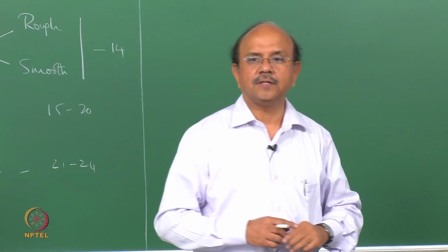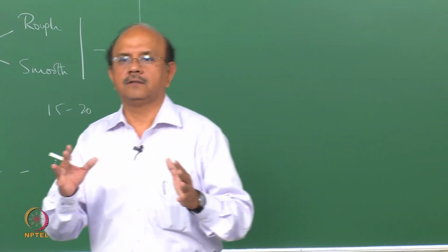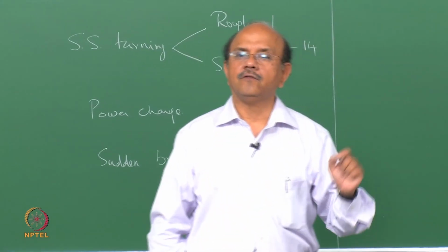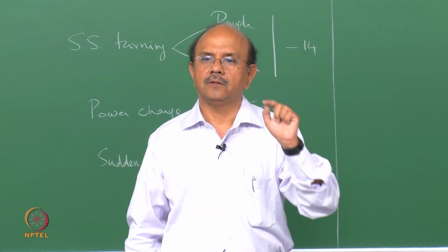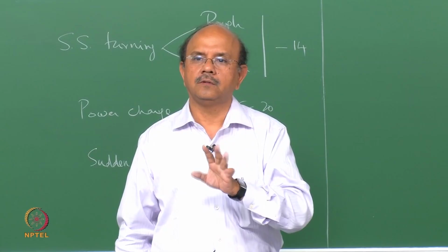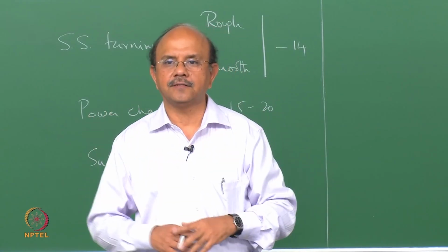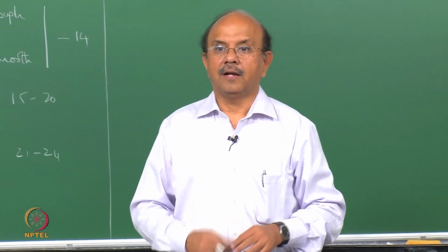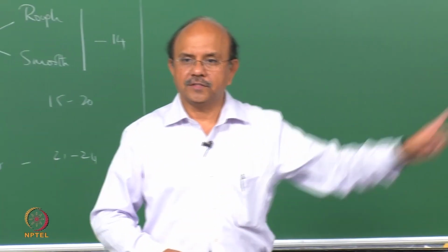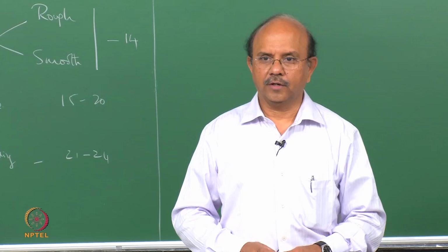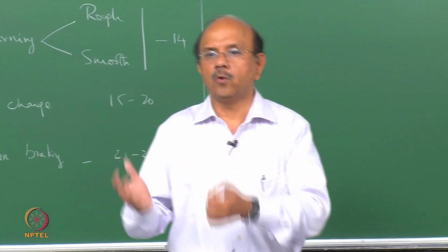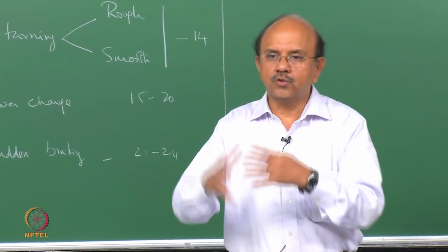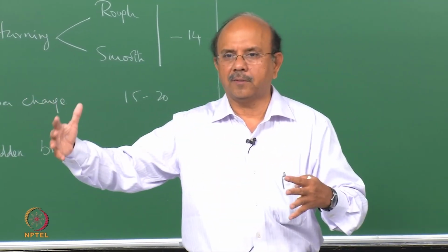I'll say natural frequency. I'm going to take, say, 3 or 4 cars, whose natural frequency at yaw varies from 1.6, 1.8, 2, and 2.4. Let's say that I take these cars and I give them to the drivers, and ask a number of questions which I had listed. How does it behave in a turn? Are you going to hold it, are you losing grip, and so on and so forth. I'm going to ask them a number of questions.